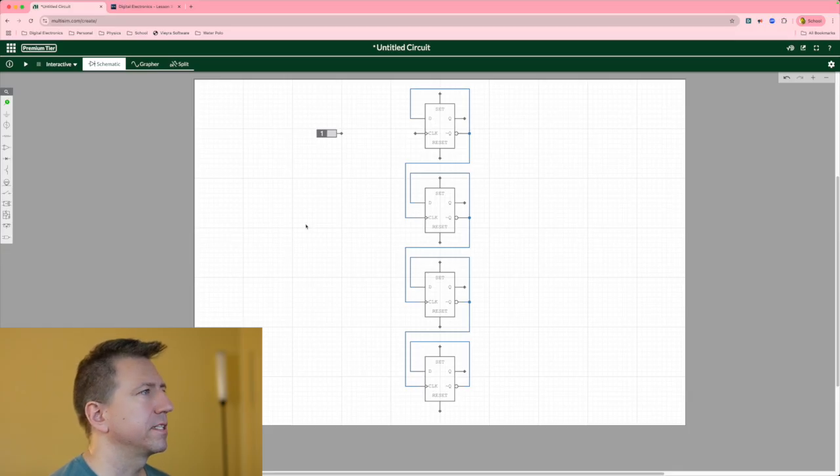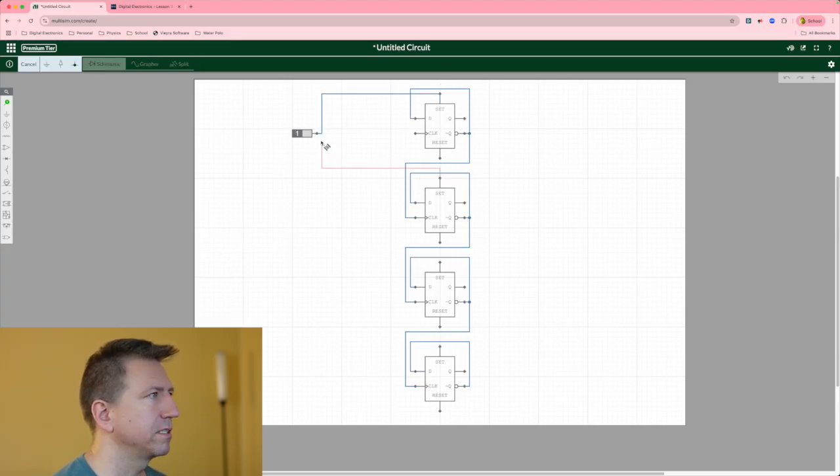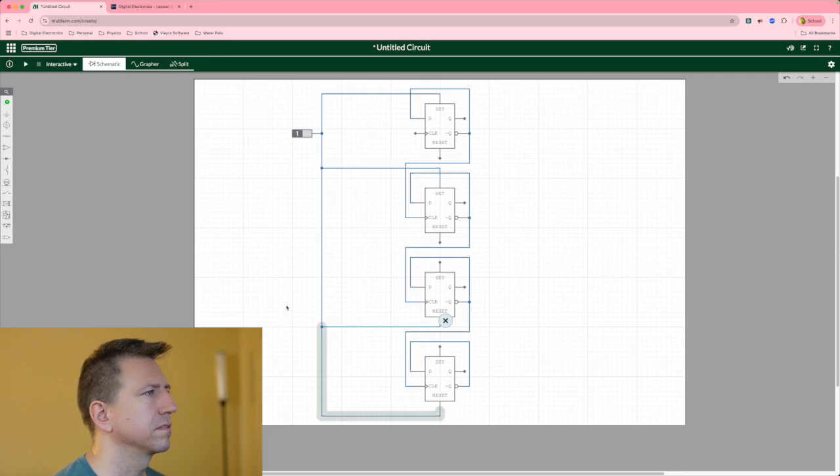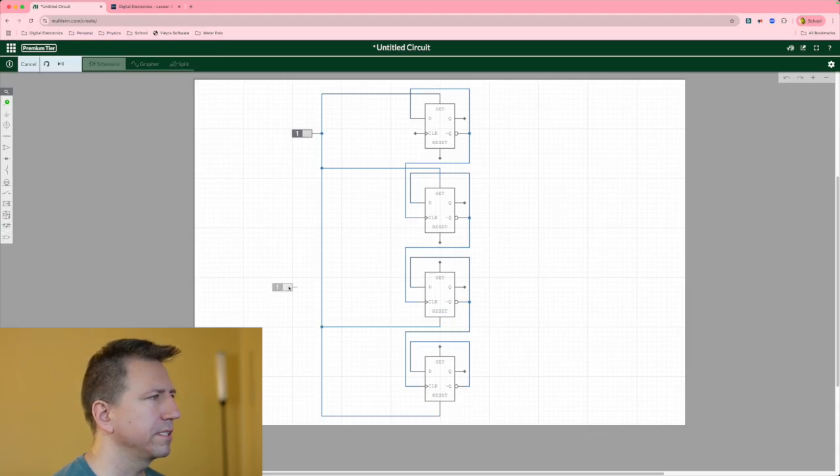First, the set circuit is going to be making this into a 3. I'm just going to use this for the time being to help build that set circuit. We're going to have these both be set to 1, and then these two be reset to 0. We also need to have the other ones tied to 0, so I'm going to use a second digital constant to do that, and I'll put it on this side too.